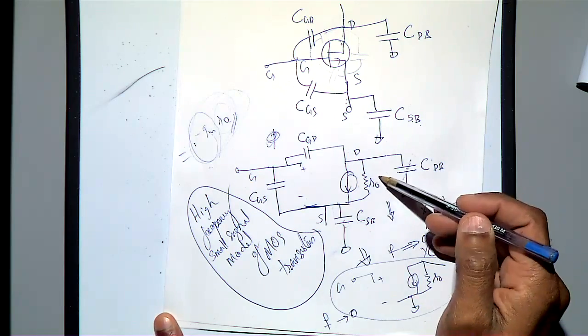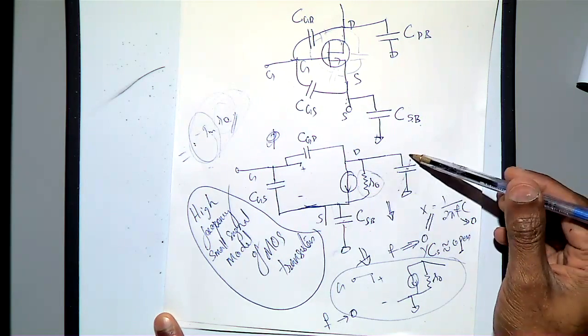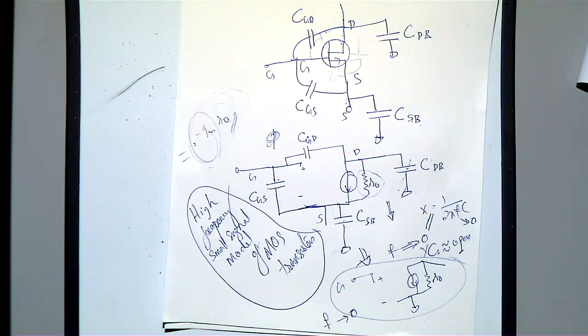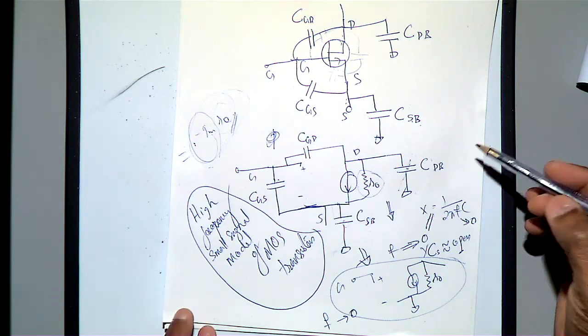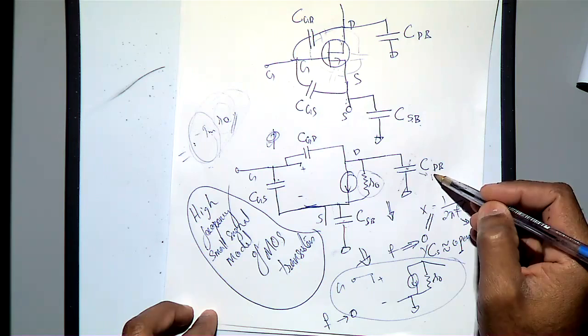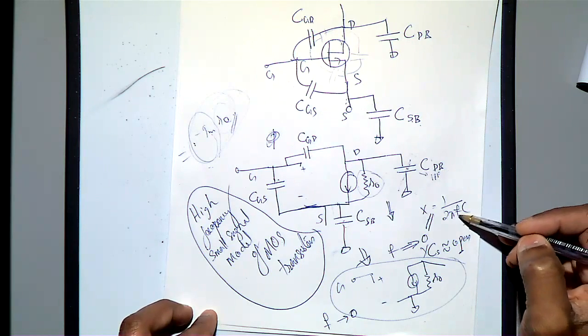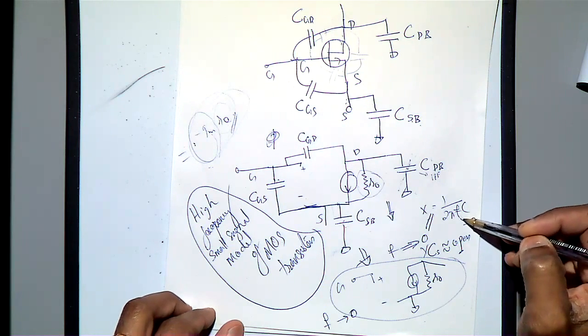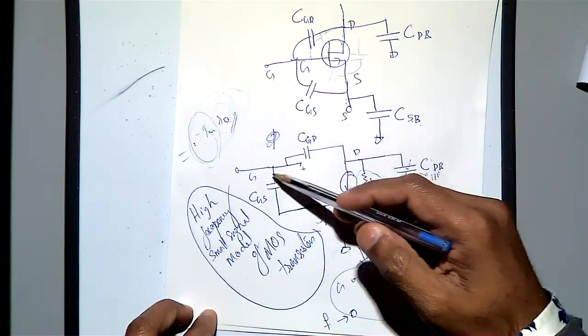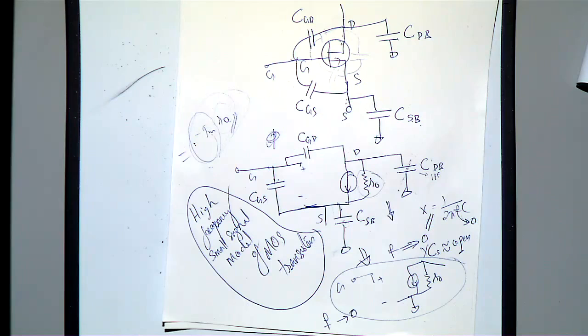Because even if we both got the same RO, if we get these capacitors different, it means what you designed got another frequency cutoff, and what I designed got another frequency cutoff. For example, if these capacitances are very, very small, like in picofarads, then what will happen? Then this will be kind of shorting all your signal. So that is the reason, it depends upon the capacitor value.